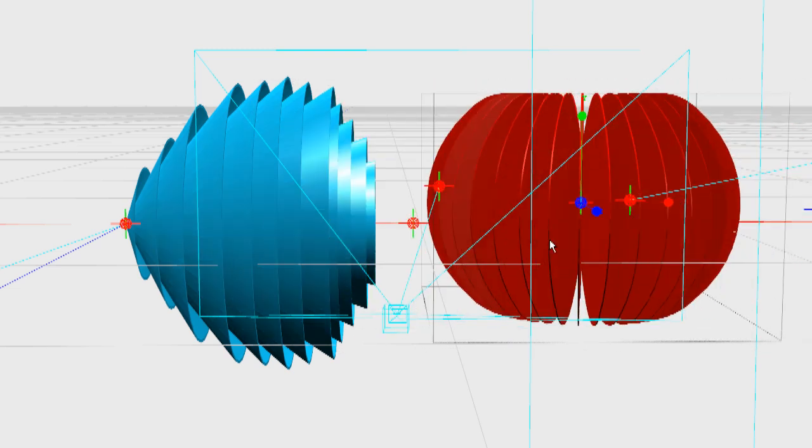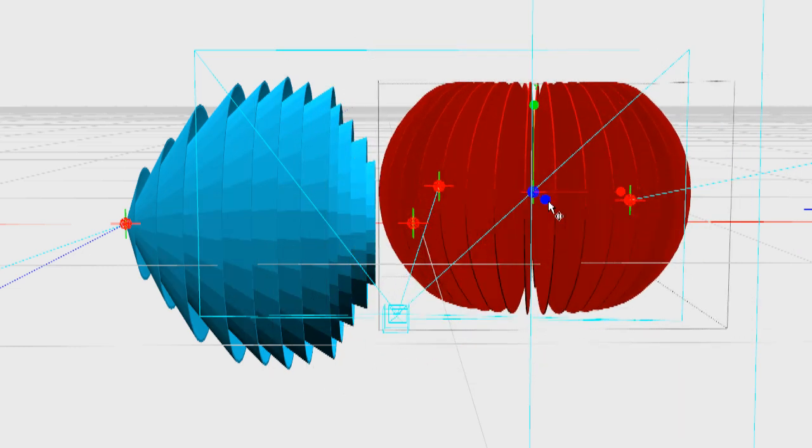One's circular, one's vertical. However, the great thing about a circularly polarized antenna is that your loss, instead of it being 26 decibel, remember, if you've got a horizontal antenna trying to talk to a vertical antenna, you've got a 26 dB loss, which is massive. However, the linear, as in vertical or horizontal polarization, versus a circular mismatch, is only 3 decibel. And the great thing is that with a circularly polarized antenna, because of the way it works, you're never going to get less than 3 decibel loss, no matter what your orientation is on the plane.